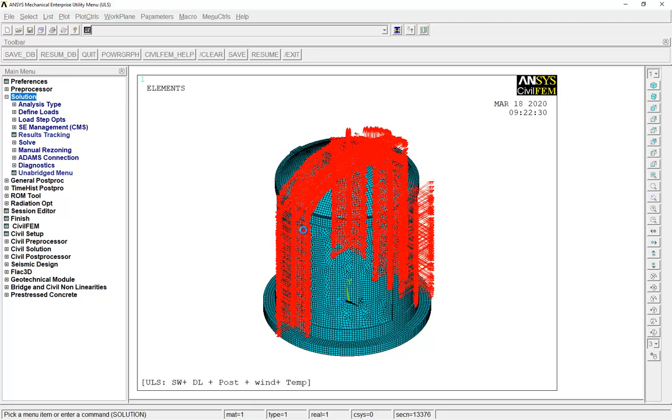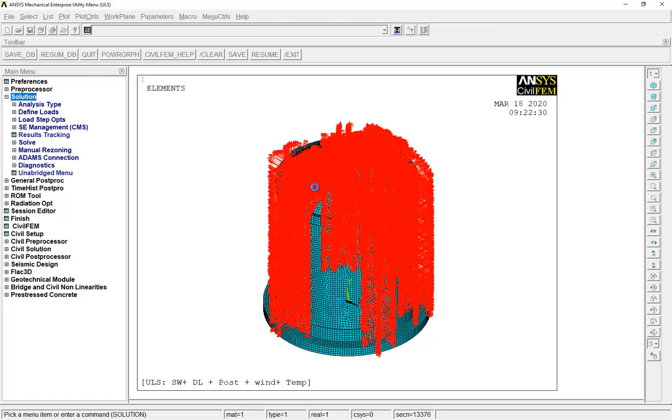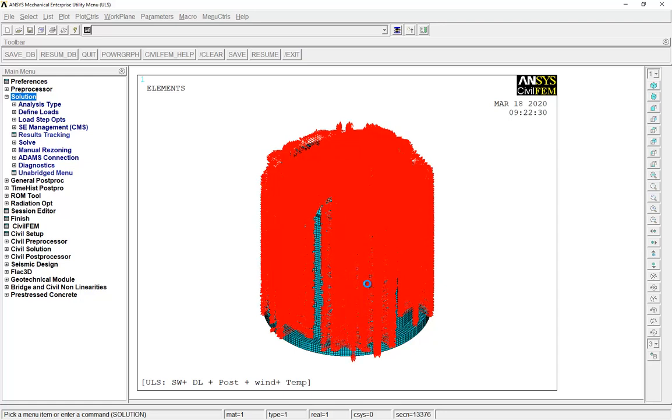You can see here the first U tendon, the second U tendon, and the order of these loads can also be defined. As these are equivalent forces that you are applying to the model, these forces can be solved apart in different load steps, can be combined, and also if you are performing a construction process, you can add these forces, combining the construction process and the element activation and deactivation of different parts with these tendons, so you can perform a very detailed construction process.